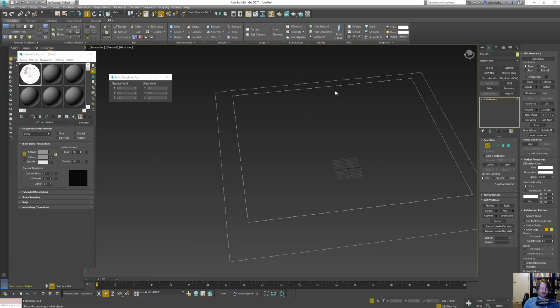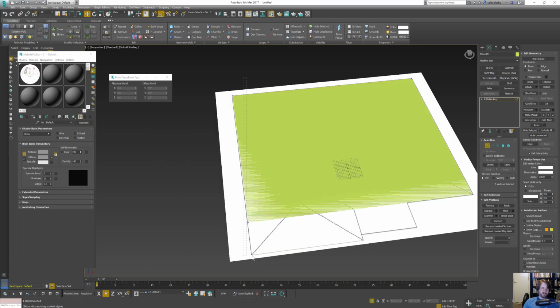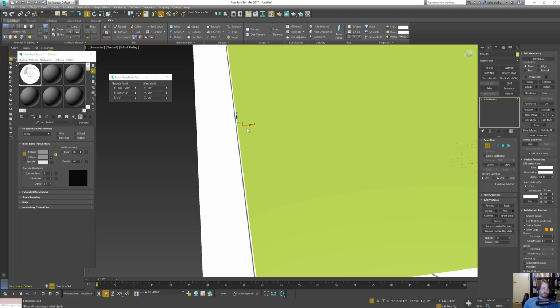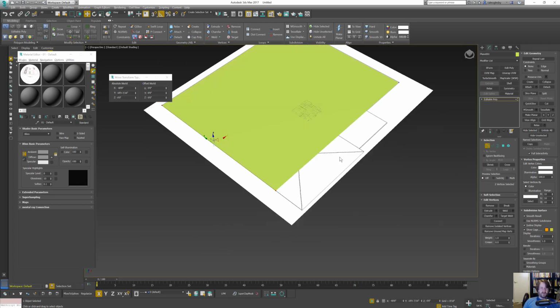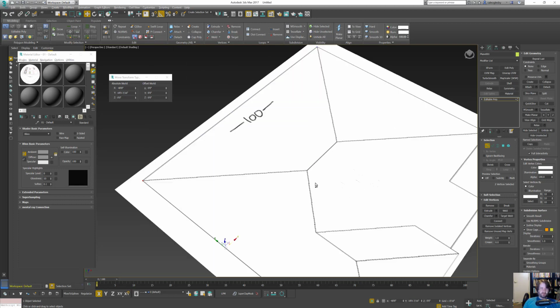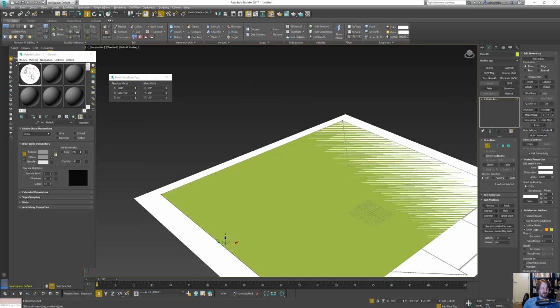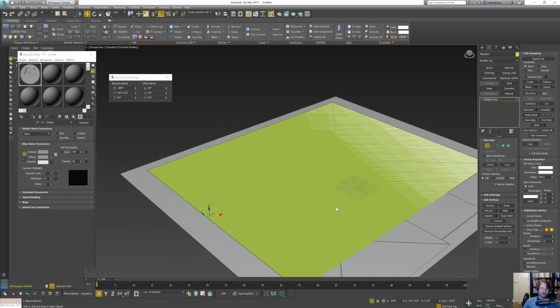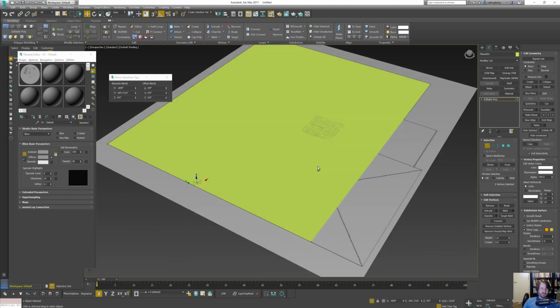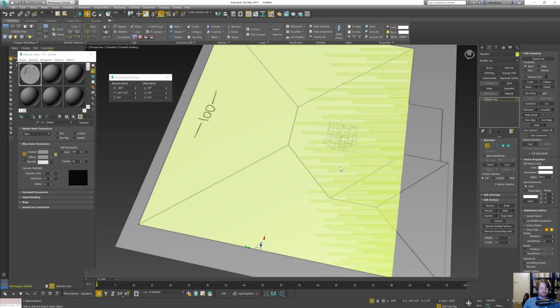You would not want all your polygons and stuff, the 4x4 grid, because it would throw you off very quickly for what we're going to do here. Okay, cool. So we have that. If you hit Alt-X, you can see through it if it's hard to see, or in here you can lower your opacity to like 50, and you can kind of manipulate how you see your information.